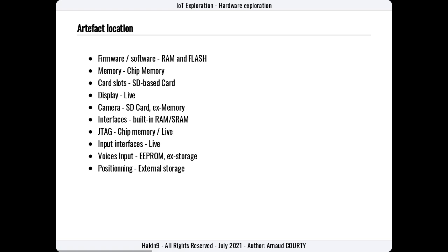In the case of external storage, like live memory for software, maybe an EEPROM should be identified and easily dumped offline. You can try to put some probes on the chips, or in the case of a QFP mounting, for example, try to unsolder it. In the case of the presence of a card slot, you can easily remove it and do all the forensic investigation on the laboratory computer.